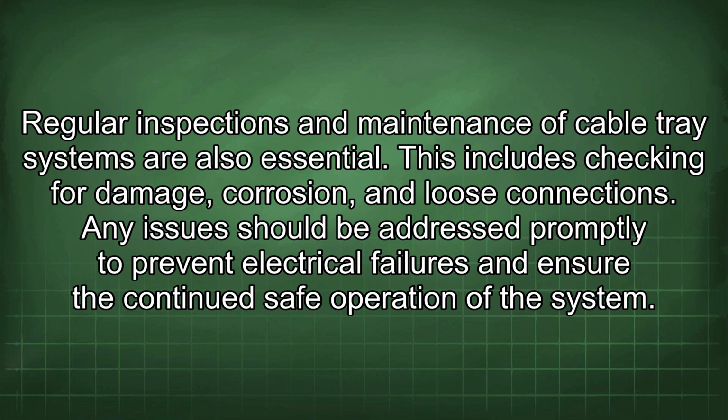Regular inspections and maintenance of cable tray systems are also essential. This includes checking for damage, corrosion, and loose connections. Any issues should be addressed promptly to prevent electrical failures and ensure the continued safe operation of the system.